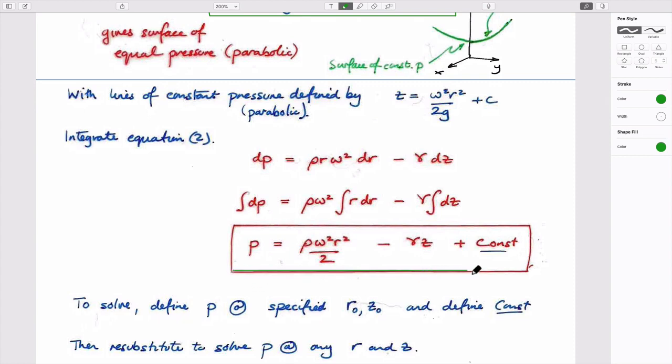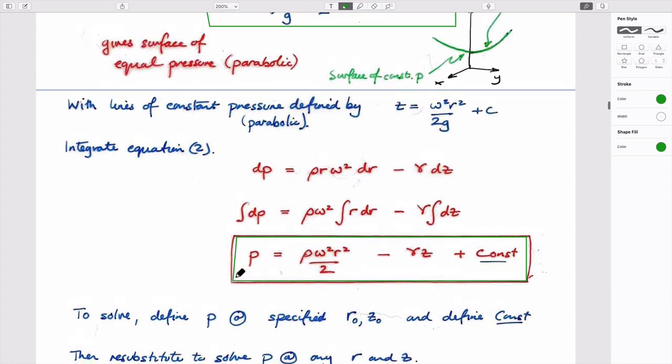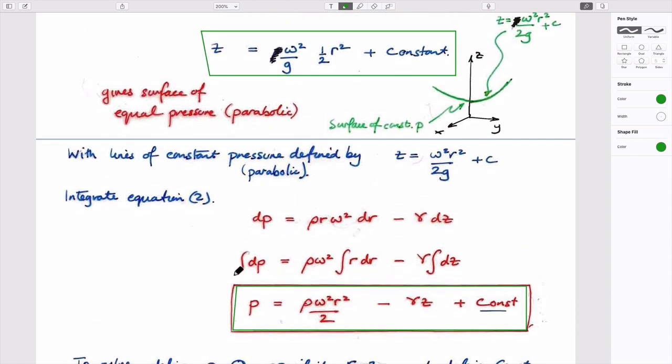And so these are kind of standard results. They're obtained in exactly the same way as we did it for the linear case to get two things. One, in the linear case, we want to know the inclination of the free surface. It was a plane, horizontal plane, that reacts to accelerating. It goes up at the back as we accelerate in the other direction. Here it doesn't happen to be a plane, it happens to be kind of parabolic. It varies as r squared.